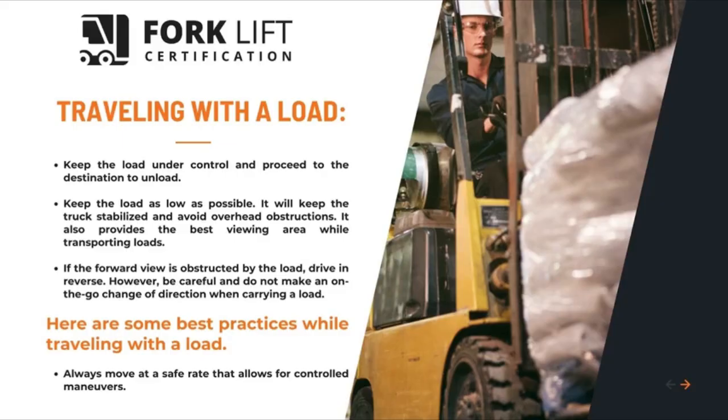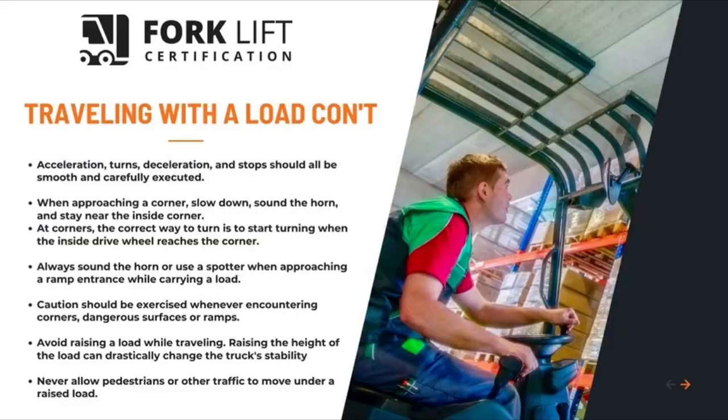Always move at a safe rate that allows for controlled maneuvers. Acceleration, turns, deceleration, and stops should all be smooth and carefully executed. When approaching a corner, slow down, sound the horn, and stay near the inside corner. At corners, the correct way to turn is to start turning when the inside drive wheel reaches the corner.